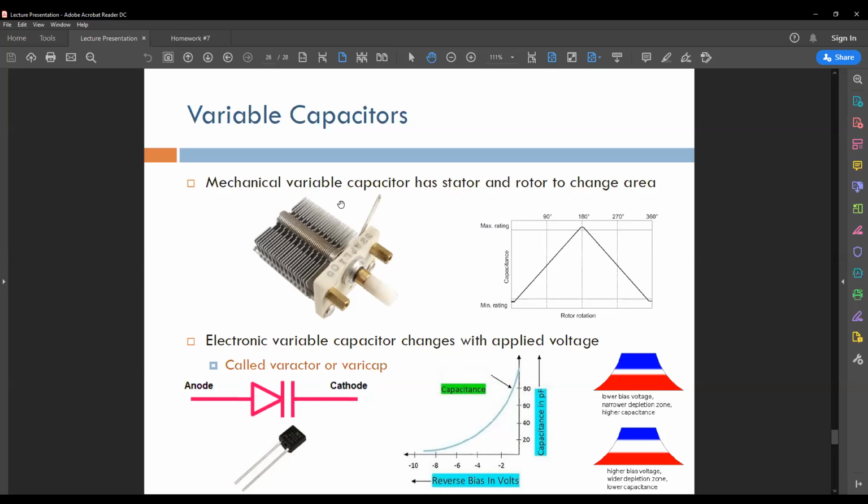How can you get a particular channel? You have all kinds of channels transmitted from the broadcasting antenna. Each radio station has a particular frequency. What you need to do is use a capacitor and an inductor and tweak them together so that you can match the resonance frequency of the station you want to hear and start listening. Okay, this was done before using a knob.